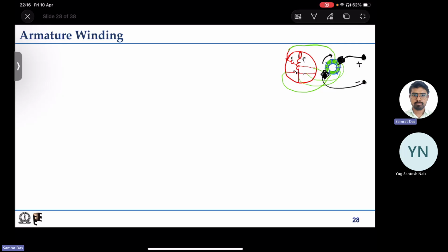And similar to that, if we look at all the coils, say this is an armature coil, the current say IA1, and this is say coil 1. So if you look at the current waveform of any coil, it will be like this because the induced EMF is something like this, a quasi-square wave.